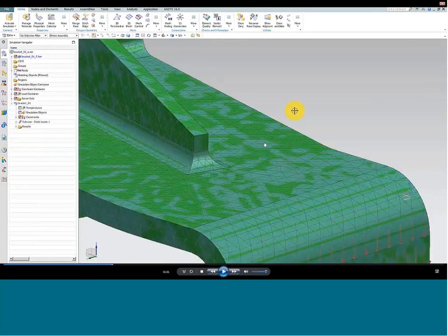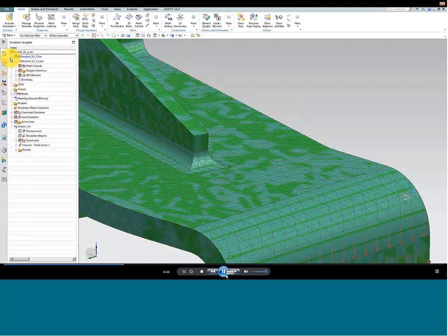You'll observe there's two slightly different shades of green here. One shade represents the elements, and the other shade represents the polygon geometry. And to prove to you that the two have now been brought back together, if I expand the FEM node in the tree in the Simulation Navigator, now you'll notice we do see a branch for polygon geometry. So the process has begun.